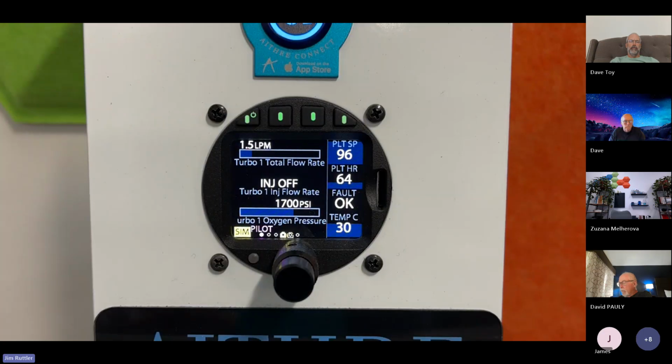So if you just open up the Aithre Connect app and make sure that the Lyrian or the Shield or the Metis is paired to the Aithre Connect app, it will automatically reinforce and relay that data to the ATD via the HealthView data bridge. And one other note is that if you are running more than 2 Lyrian oximeters, say you've got a co-pilot and people in the back and you're monitoring everybody's blood oxygen level, then you must have the Aithre Connect app open, at least running in the background, as the app keeps track of which pulse oximeter goes to which occupant of the aircraft and then relays that order to the HealthView data bridge to keep it in order.